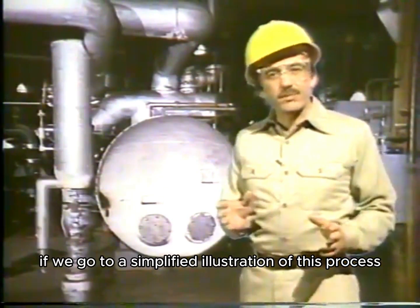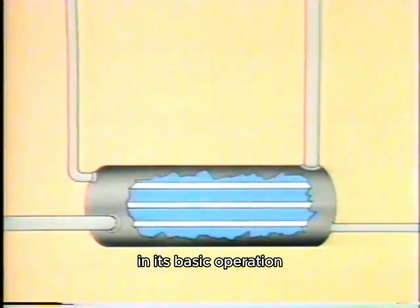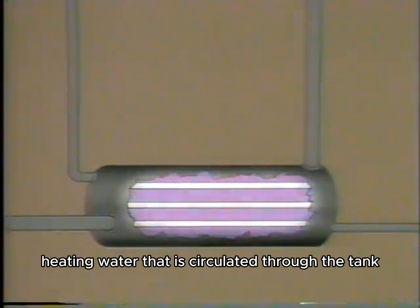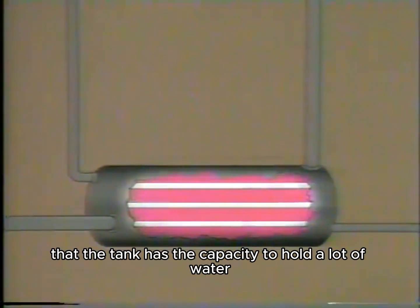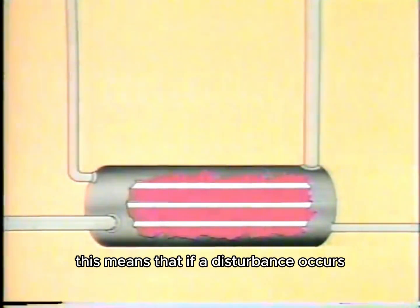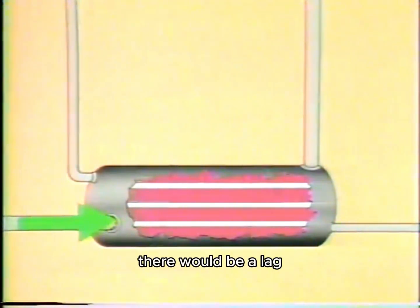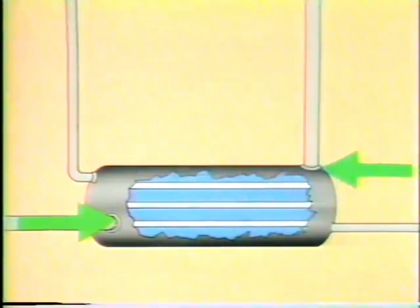Now, if we go to a simplified illustration of this process, we can see how it works. In its basic operation, steam flows through tubes inside the tank, heating water that is circulated through the tank and around the tubes. Now, one characteristic of this process is that the tank has the capacity to hold a lot of water. Large amounts of water have the capacity to store large amounts of heat. This means that if a disturbance occurs that changes the water temperature at the input, there would be a lag between the time the disturbance occurs and the time it's sensed at the output.